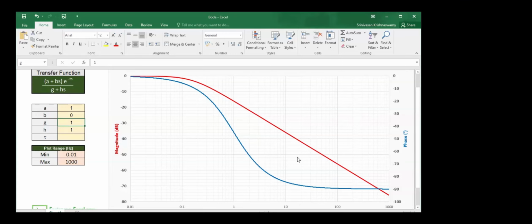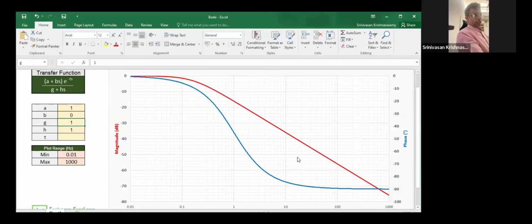All these filters, especially first order or second order filters, can be implemented in hardware. There are two kinds of things that can be done: one is passive systems, and one is active systems. Passive systems are typically those that do not involve any power generation, so you typically have them with LRC components. Active parts are those that involve amplification, and they would include amplifiers.